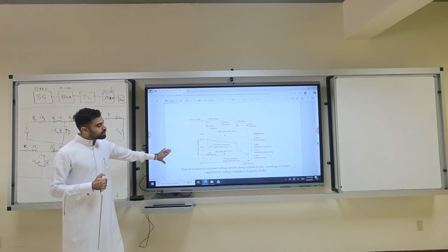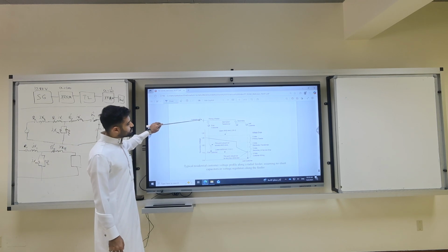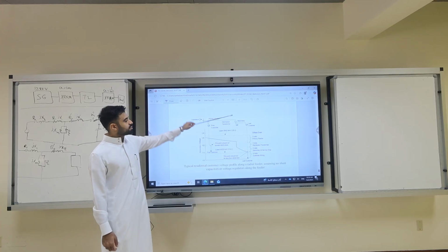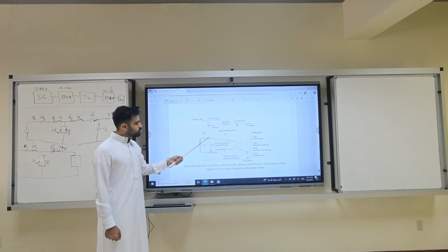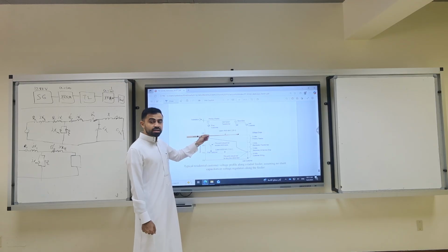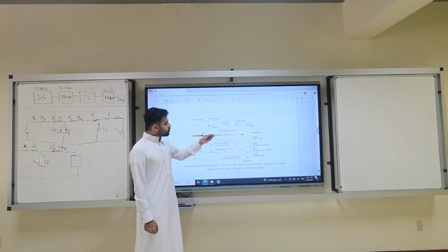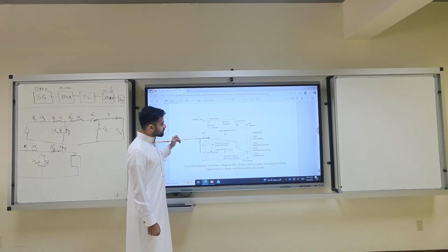Last thing is power quality. Let's look at this. We have a substation. We have the feeder. The first customer has a transformer. This is from primary to secondary. And the first customer has around 125 volts. So the ANSI standard, this is US, is 126, 114. It has to stay within this band. So 126, so here it gives you 125. There is a voltage drop here.